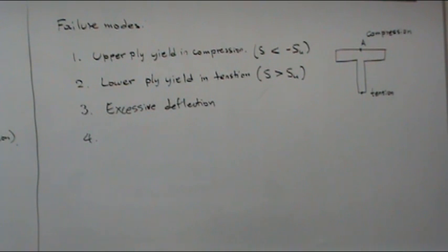And buckling occurs under compression, so you've got to evaluate if the flange will buckle, or maybe even the web can fail. The upper part of the web may fail, okay, because this part is still under compression, so this part you may have local buckling.